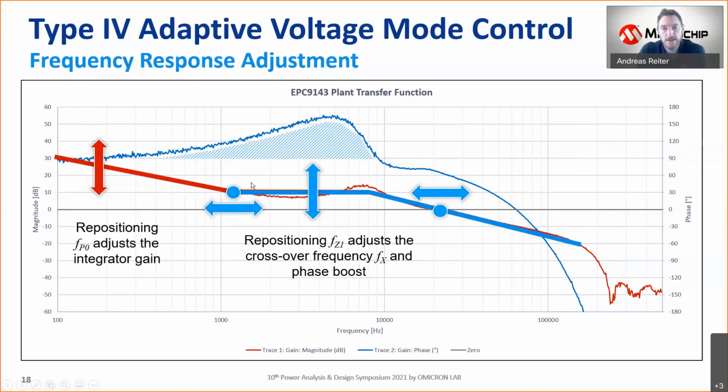So the gain will start to drop from a higher level and then cross at a later point, increasing the total bandwidth with a decent positive gain offset. The same is true when I increase the pole at origin frequency, then I can push the zero out and then lower the gain level here in this region, again, coming up with exactly the desired crossover frequency.